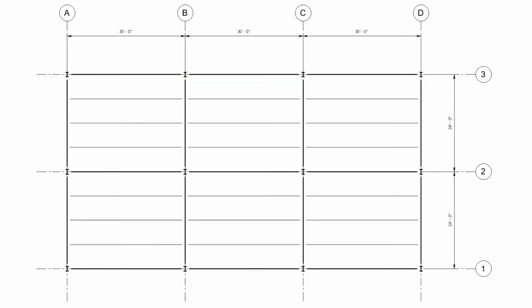Okay, one final idea is that back in our framing plan, what would we do about the columns? Well, when we look at a column, let's suppose we wanted to look at an interior column, that column there, for instance, then what we would do is go halfway between columns left and right, halfway between columns this way, halfway here, and we would scribe in our tributary area for an interior column like that.